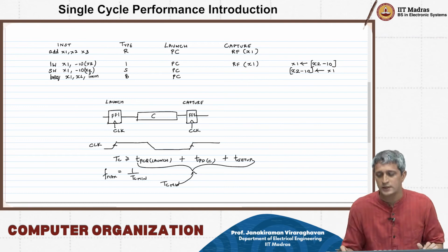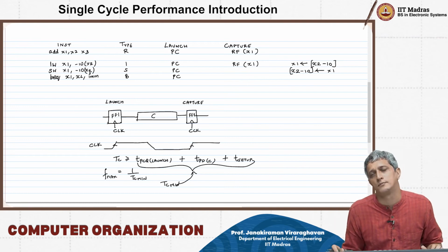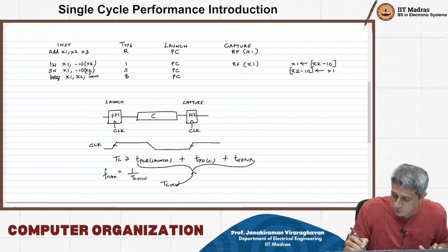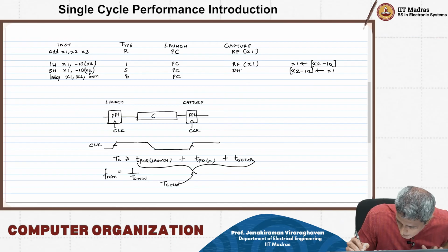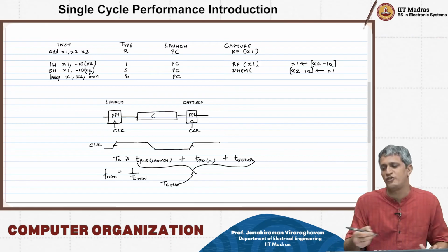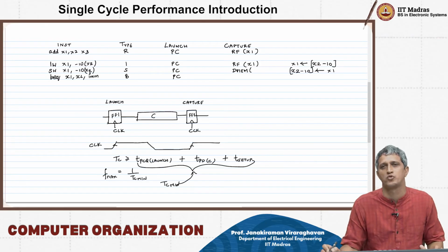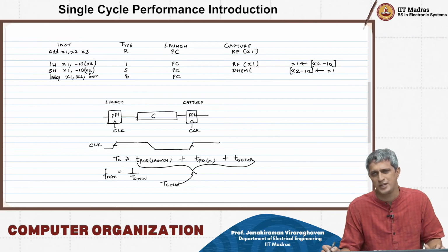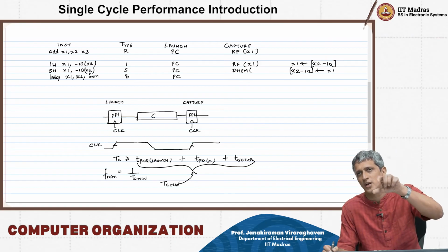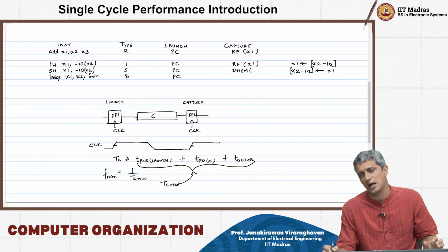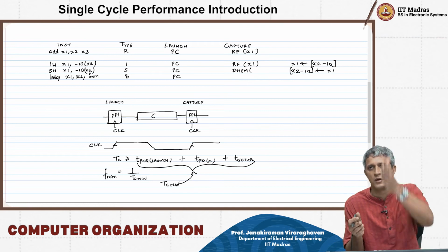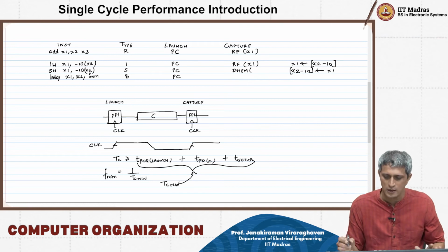Therefore, what is the capture flop that we are talking about? It turns out that this is your data memory. Whichever address we are talking about, x2 minus 10 in this case, happens to be the memory location which is going to capture this data, and therefore the data has to be ready some setup time before the clock edge there. That's the key point.